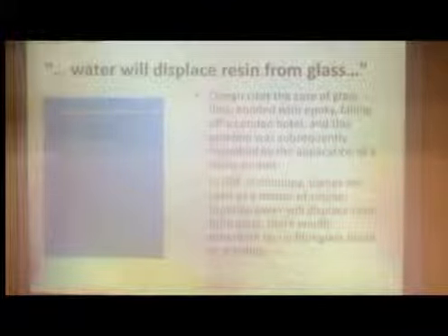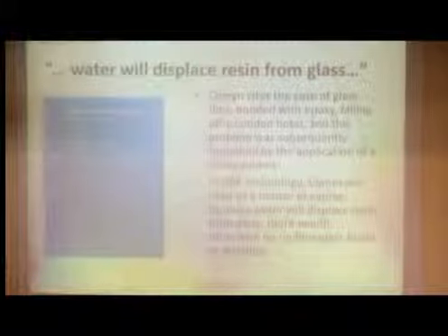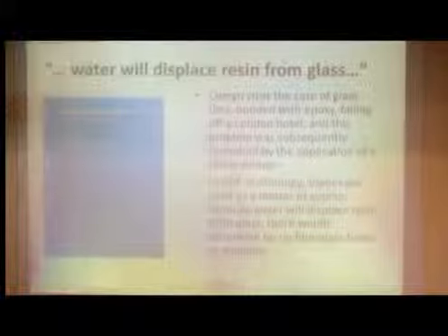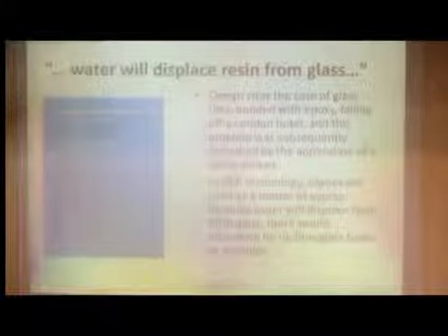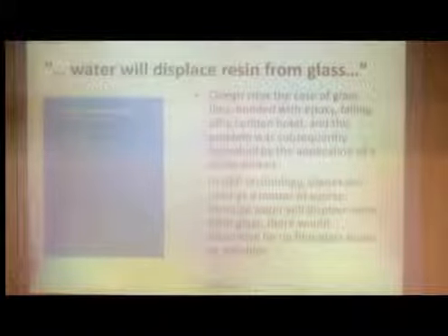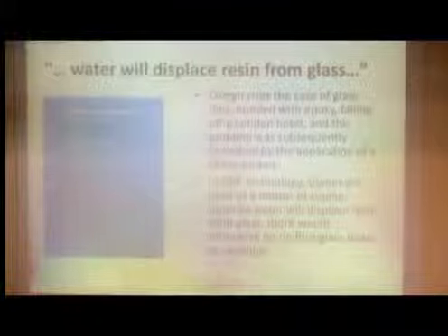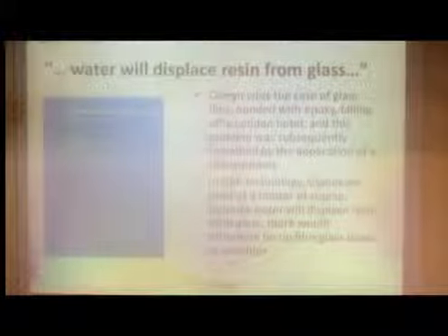And it's unfortunate for the Savoy or whatever it was that the epoxy much prefers to hold on to water than it does to glass. And so instead of the epoxy sticking the glass all over the walls, it stuck the water all over the walls, and all the glass crashed onto the floor. So we know that we have a problem there.